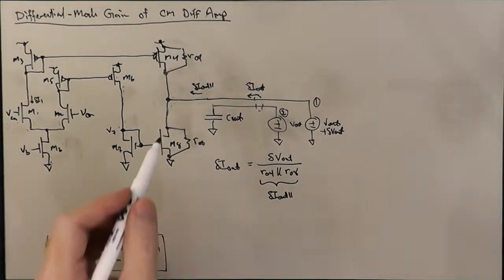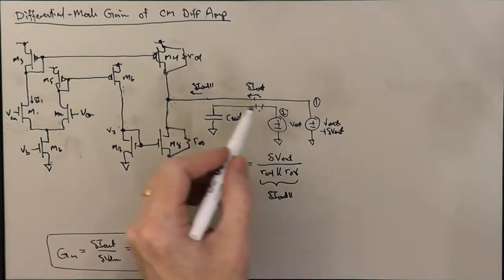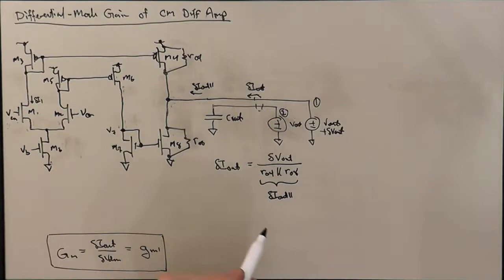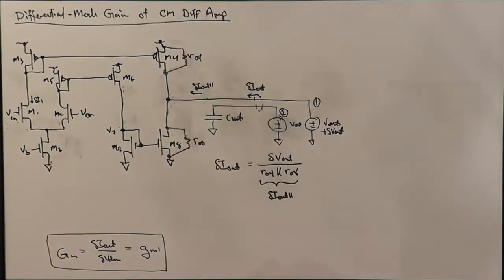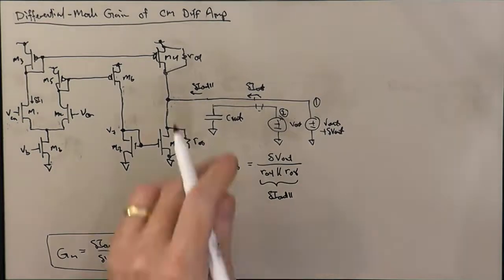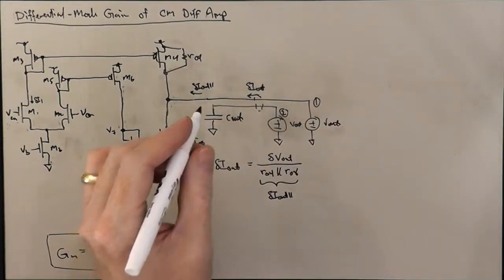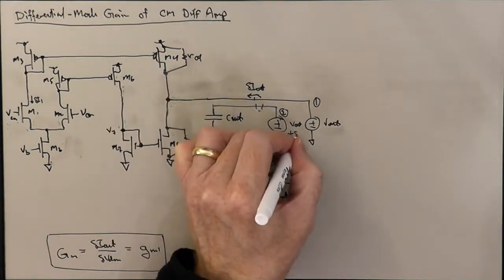And notice that that current will not excite any current flowing in this other loop in the circuit, which is completely isolated from it, since we split V out into 2 replica sources. And so we'll move on to branch 2, or delta V out here.